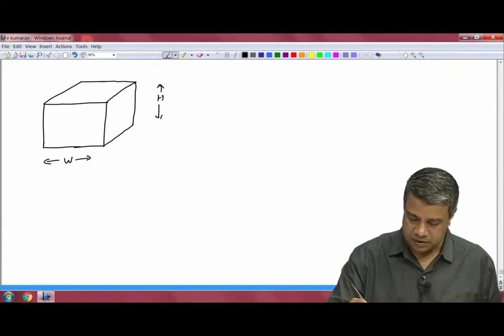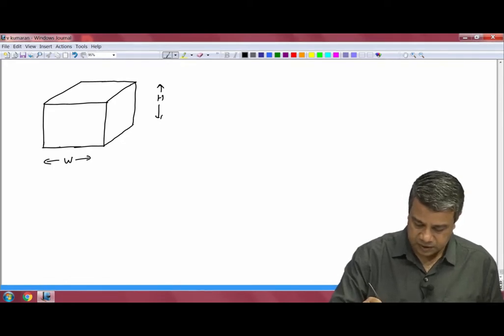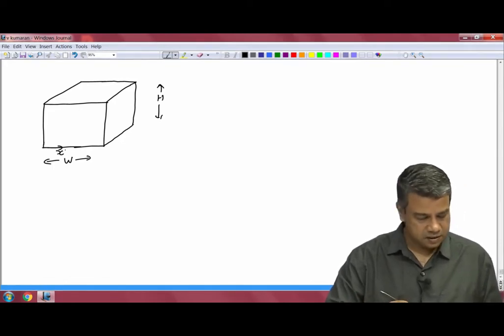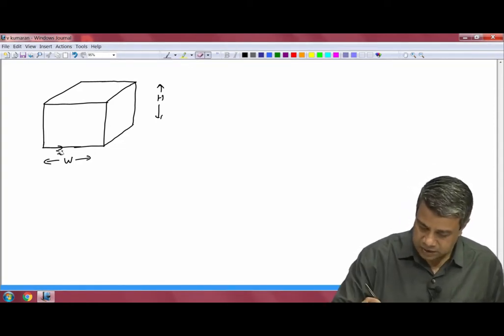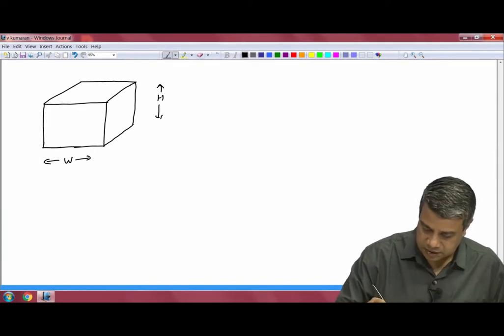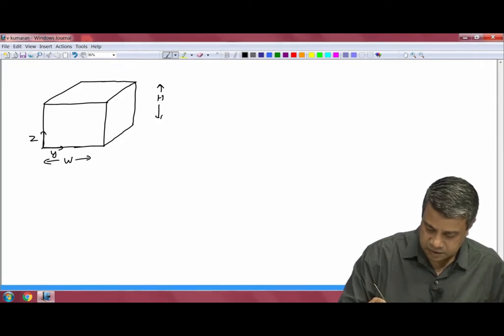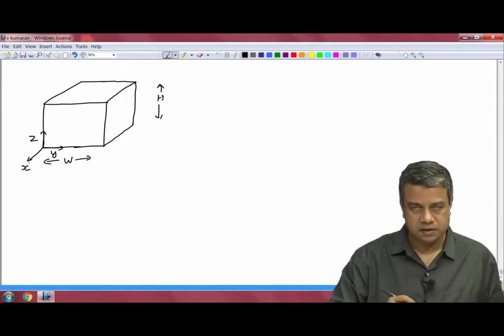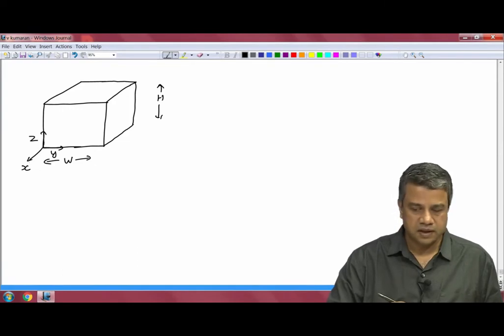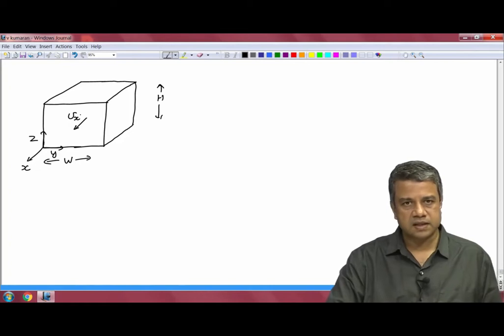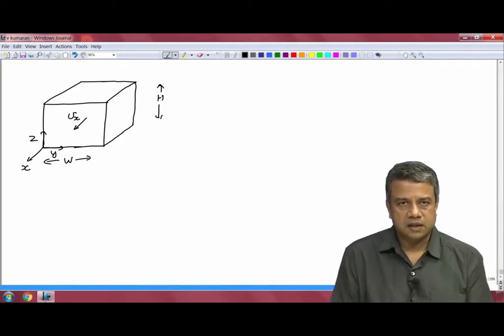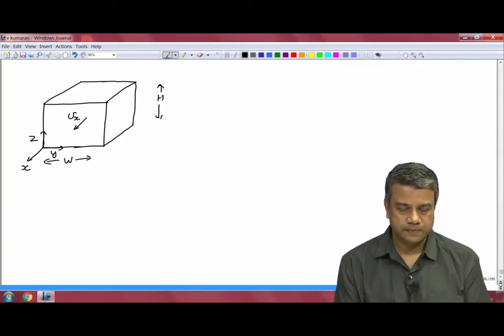So, the directions in this case are: y is in the horizontal direction, please correct that, and z is in the vertical direction, and x is in the streamwise direction. So, there is flow in the x direction, there is a velocity Vx which is flowing in the x direction due to a pressure gradient exerted across the ends of the channel.